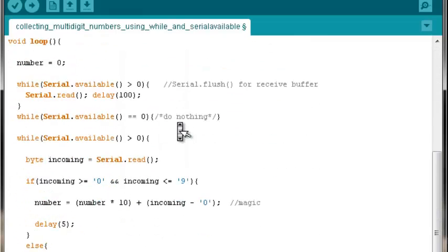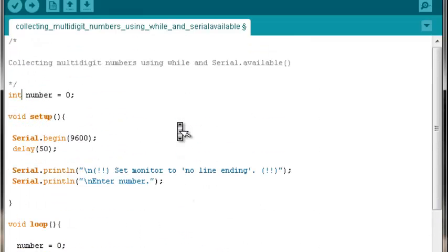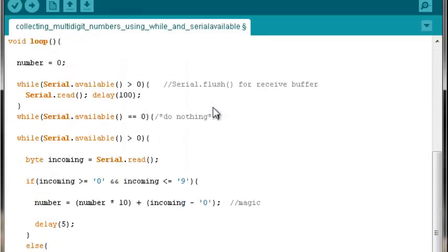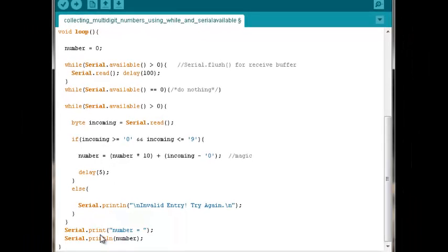So that being said, here's the program. It works. I'll slow down so if anyone wants to pause the screen and record and copy any of this stuff. There's all that's happening. We've got one global variable. That's what's happening in setup. And then in void loop, there's the code. And really, the magic to it all occurs from this while down to the if, because this is where there's data in the serial receive buffer in the Arduino, and then this is the processing of it.